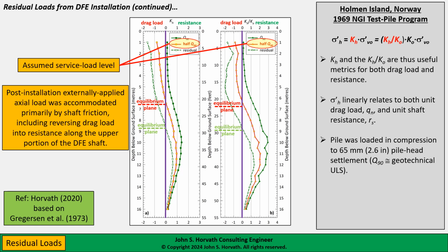But we note that even under the service load level, there is a not insignificant amount of drag load still acting on the shaft. And this is very important. What this illustrates is drag loads don't magically disappear when you apply a service load to a deep foundation element. They're out of sight and therefore out of mind, but they are still there.